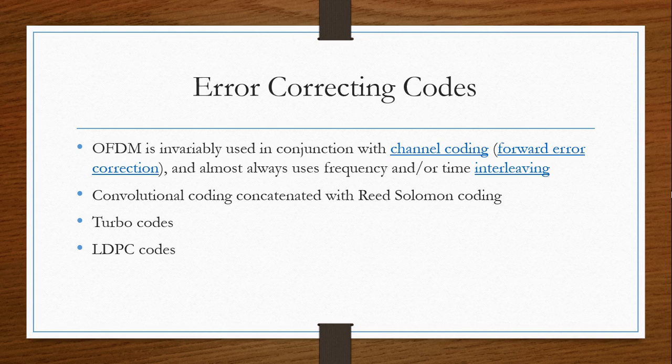The reason why interleaving is used on OFDM is to attempt to spread the errors out in the bit stream that is presented to the error correction decoder, because when such decoders are presented with a high concentration of errors, the decoder is unable to correct all the bit errors and a burst of uncorrected errors occurs. A similar design of the audio data encoding makes compact disc playback robust.